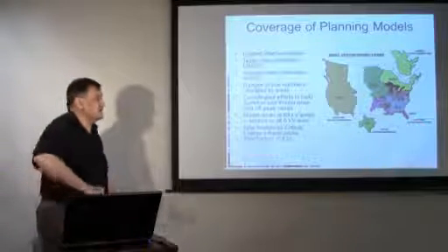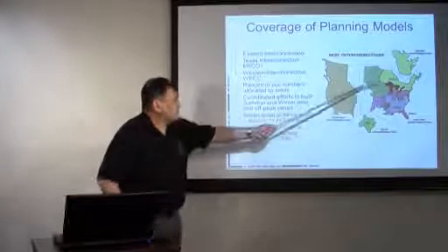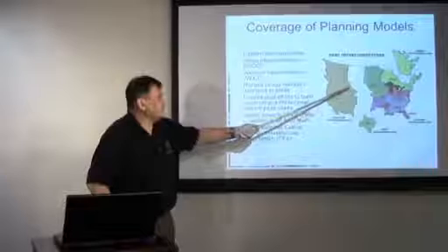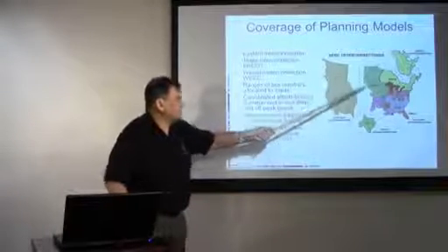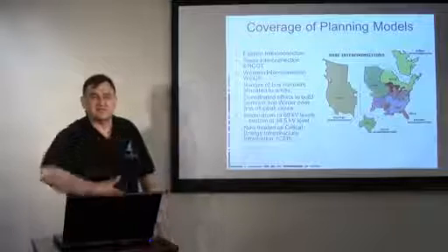For a DC line, you can pretty much assume that a constant amount of power is going to be transferred across that line, and you can run all the studies on this interconnection without worrying about what's happening on the other side of that DC line.